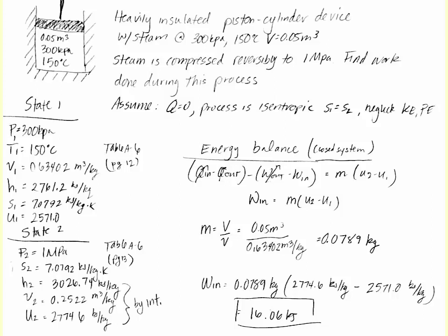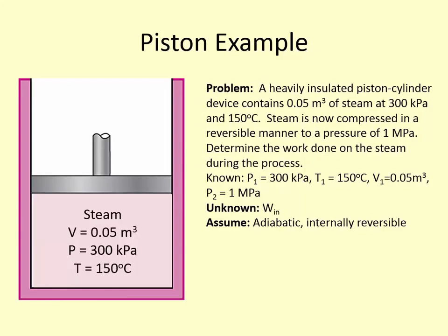We don't have constant pressure in this case, and there's no heat transfer, so we don't have anything else to balance out with a work term. So that's where that comes from. The base energy equation is always this. For a closed system, you only have a change in internal energy. For an open system, you have a change in the enthalpy, which has the flow work included in it.